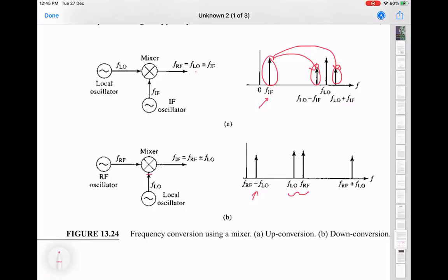That's what. We can use the method to extract the data from the RF signal to DC. I mean, we can vary that local oscillator frequency, and that will match at any particular frequency in the RF.